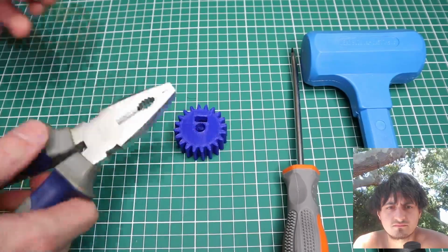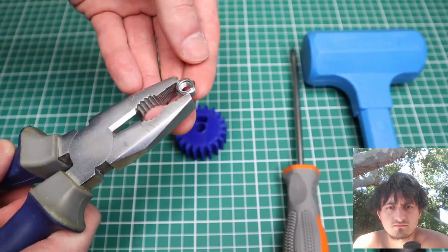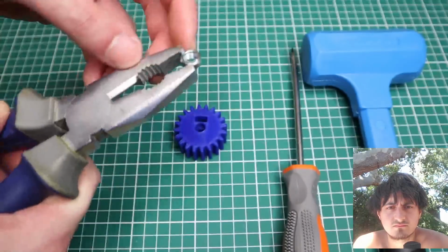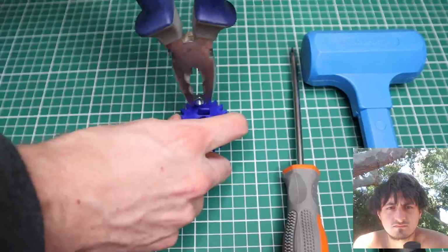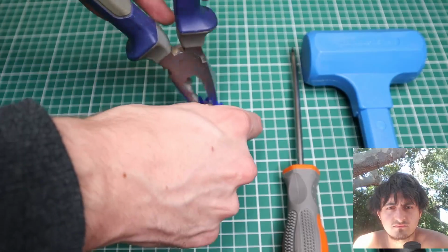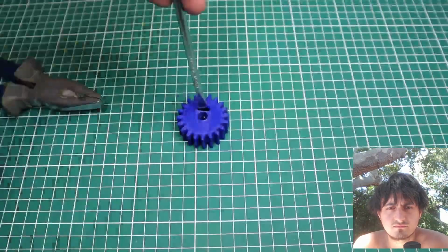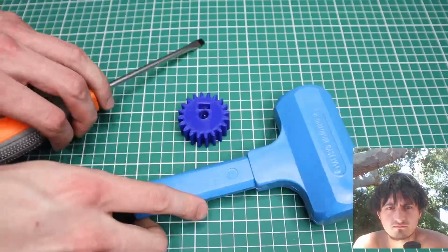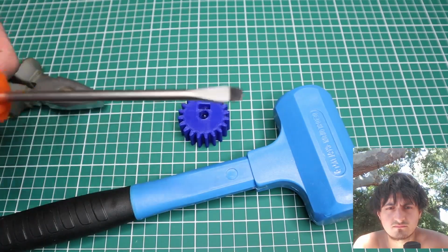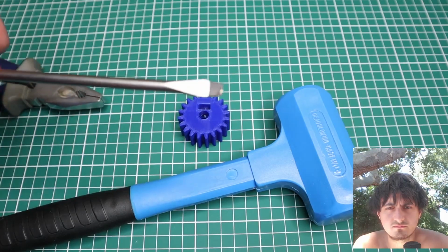If the fit is a little tighter, what you can do is put the nut inside a pair of combination pliers. If you have a pair of parallel pliers, that would be better. And then leave a little bit of the flats sticking out of the jaw. You can then keep the nut upright as you insert it into the hole. Finally, if you need to drive the nut home to the bottom of the pocket, what you can do is grab a screwdriver and just tap it home with a hammer. And in that way, you can ensure that the nut goes all the way to the bottom of the pocket. You will damage your screwdriver a little bit, but this is a 2-euro screwdriver, so see if I care.